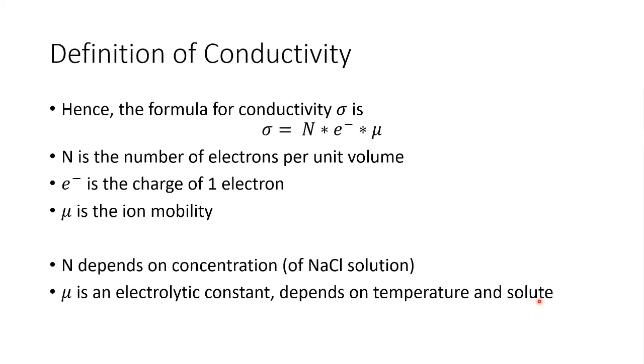So I advise you, for your detector building this year, to also include a small temperature probe. You'll have to build on your device from last year if you have one, and measure the temperature and use that to correct for and determine mu. These mu values are available in books with pages and pages of numbers, called data tables, that people have gathered experimentally. And you can hard code those into your Arduino and then reference them when you measure stuff.